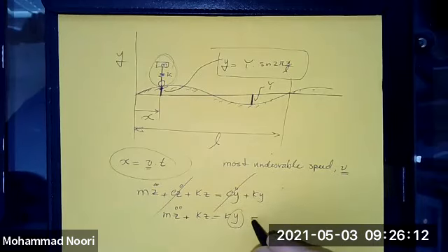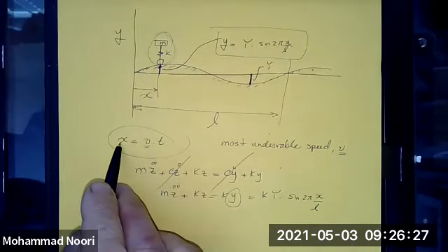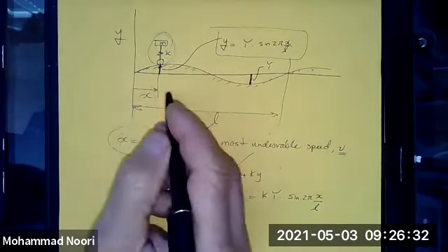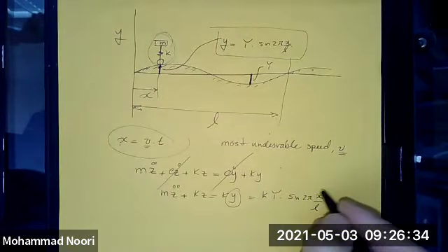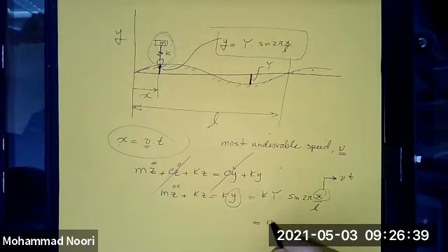So given the equation for y, we substitute for that, you have this sine of 2 pi x over L, and x is basically the distance at any point where the car is, and the car travels a distance with a constant velocity. So substituting for this as vt, the right hand side becomes ky times sine of 2 pi v over L times t.